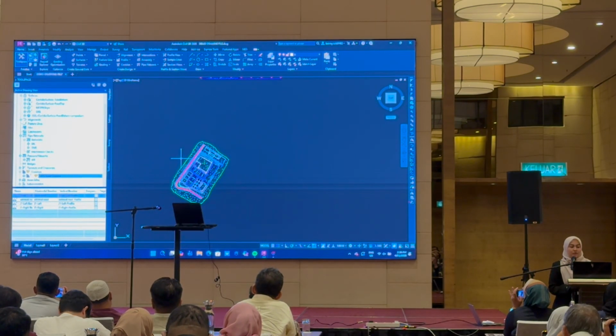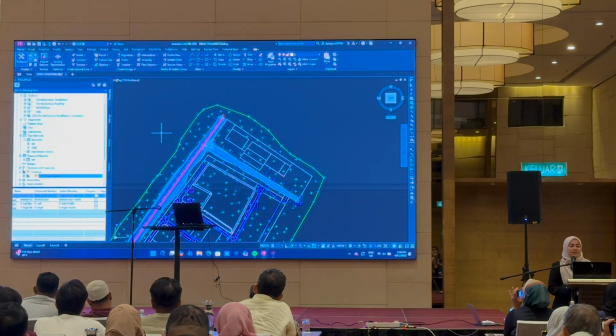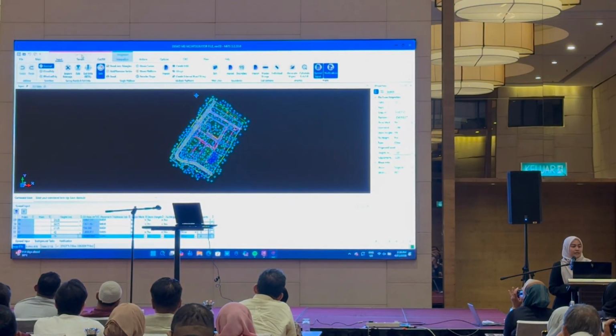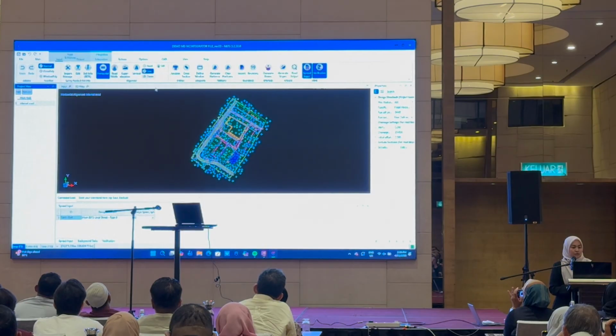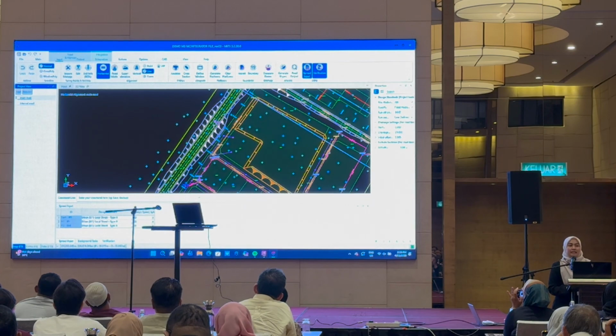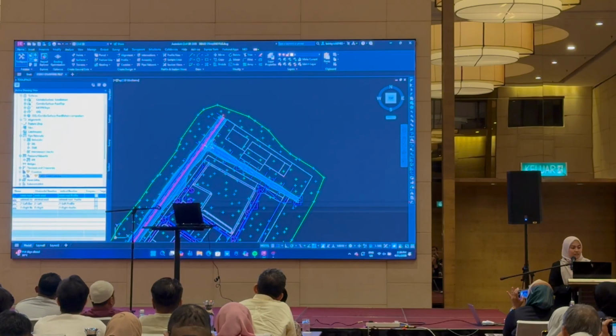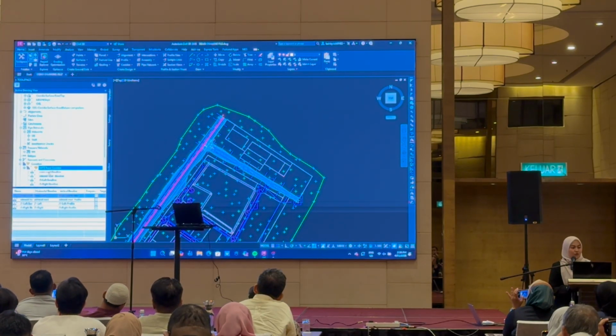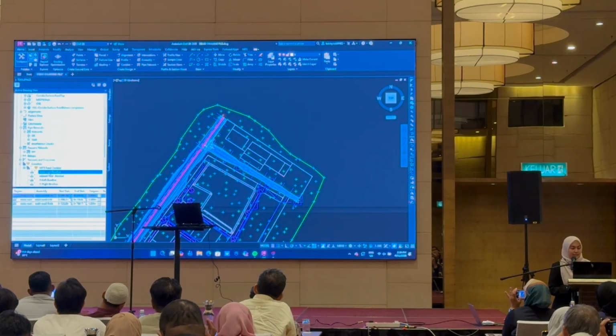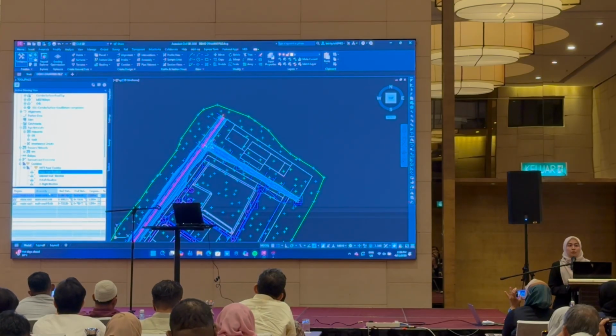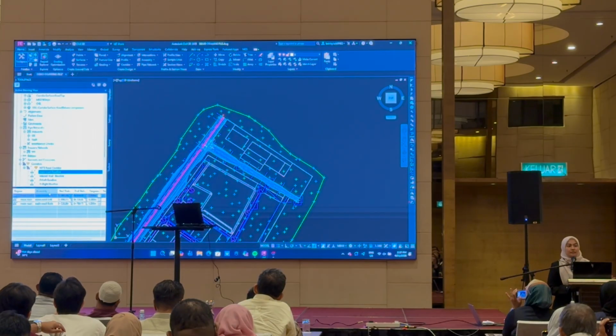And if we click on this main road, you can see this is the centerline alignment applied in this particular main road. And then if we go into the MiTS software here, and I go to this main tab and click on the road module, and then I double click on this main road, you can see the same centerline alignment. Not only that, if we go into Civil 3D, for this particular MiTS road corridor, if we expand and click on one of the baselines, for example this main road baseline here, it will list out the assembly. So this assembly is equivalent to the MiTS road width, basically where we design what the road offsets are for our design.